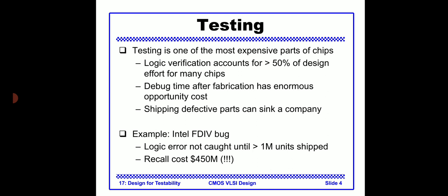Both are particularly important for ASIC design because of the black box nature of ASICs, where internal nodes are simply not accessible. They are applicable to CPLDs as well as FPGAs, but those already have built-in test features. These allow better testing of a chip, while not all the techniques need to be included in a design because they are not needed for the testing time or designing time. These DFT techniques are used to handle cases where it is very difficult or impossible to test.